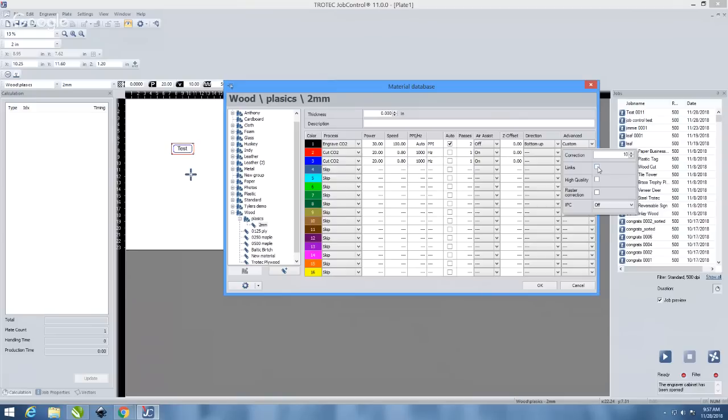This is a really important feature for certain plastics, namely the metallics. If you have this off, you'll find that if you engrave, my favorite example is the word lawyer. There's an ascender above the lowercase l or even the uppercase L, and there's a descender with the Y in the word lawyer. And you may find that the top of the L and the bottom of the Y look a little bit different in the engraving result than the rest of the word.